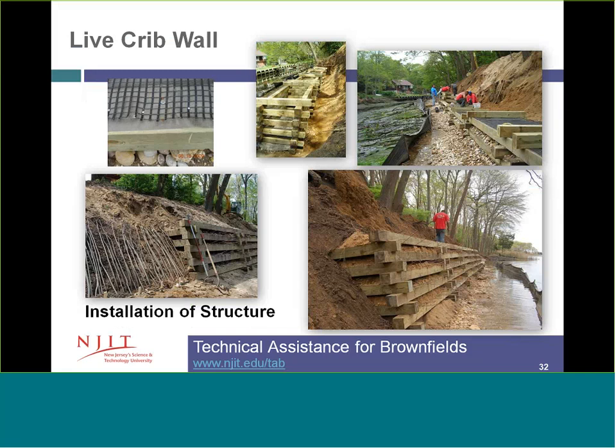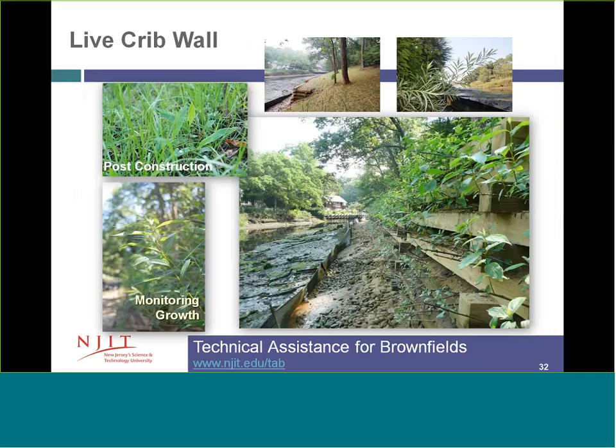This is the result several years later. The slope has been entirely stabilized and has become a green living wall, something that we had to consider because the agencies on Long Island had a moratorium on bulkheads and stone revetment on tidal creeks. And it worked out very well, and it's providing some wonderful habitat and also helped to preserve the woodland up above it.